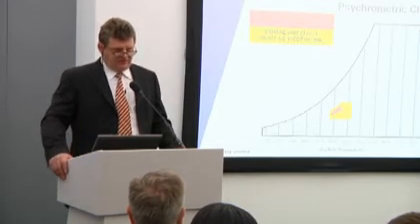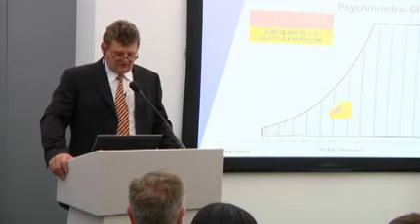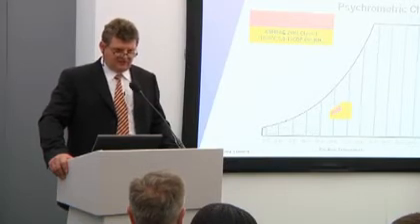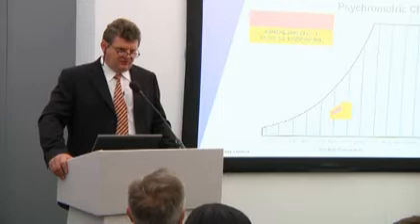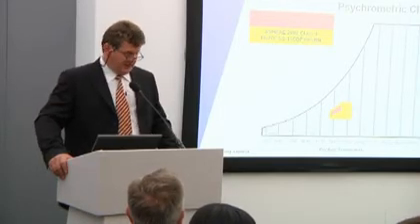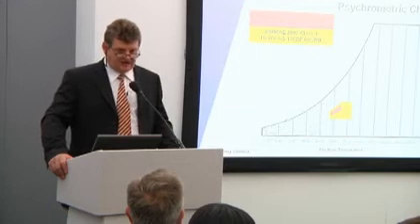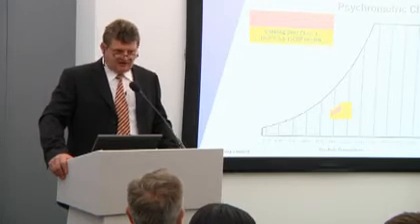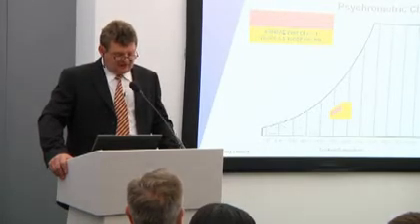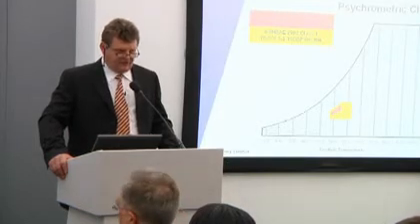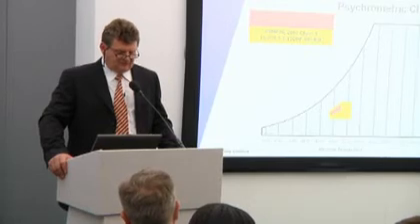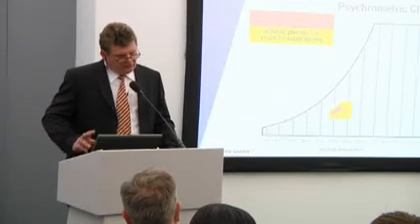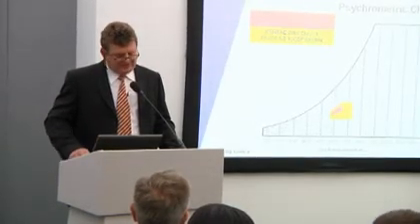However, if you go to the 2008 ASHRAE standards, the American Society of Heating, Refrigeration and Air Conditioning Engineers, they revised their specification in 2008, and this is the standard that you would use if you were going to build, let's say, a tier 4 data center of the highest standard of resilience, redundancy and reliability. Their new standards are 18 to 27 degrees and talk about dew points rather than maximum humidities, a dew point of 15 degrees centigrade in that yellow patch.